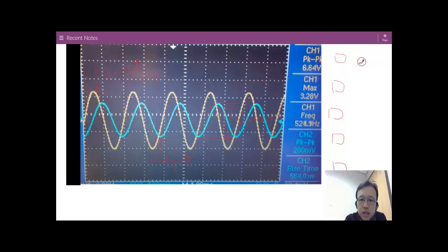So it's about 63% here. This will be your time constant tau. We got a time constant, so we can get a frequency equal to 1 over 2 pi tau. So without knowing the R and C values, just by looking at the graph, at roughly 63.2%, we can get this time constant.